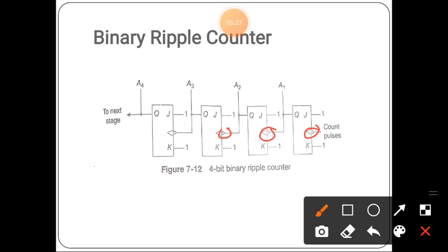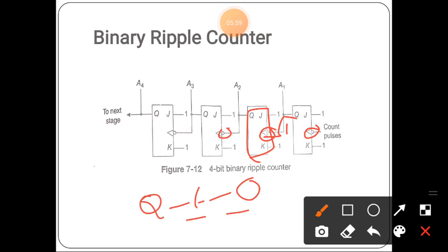That means the flip-flop state changes from one state to another during the negative-going pulse, when the output to which it is connected goes from 1 to 0. When this output is connected to the clock input, the flip-flop is triggered when the output goes from 1 to 0. If a transition from 1 to 0 occurs in the output of a flip-flop, then the next flip-flop is triggered.